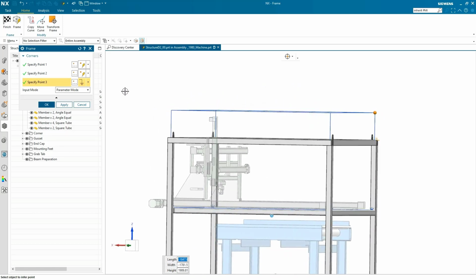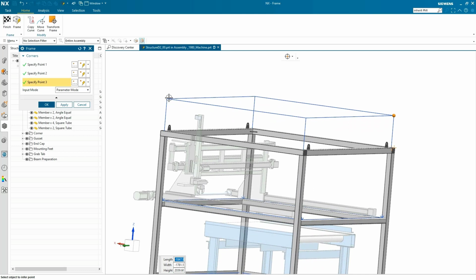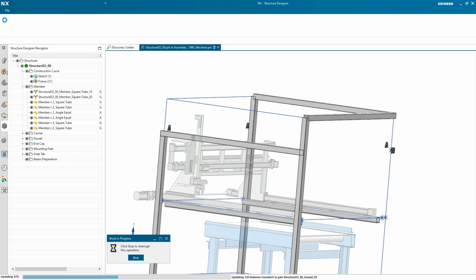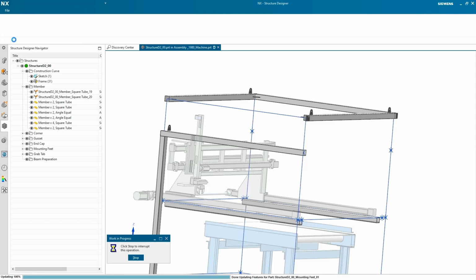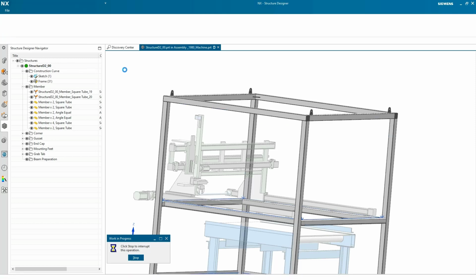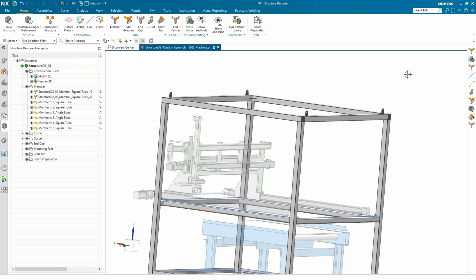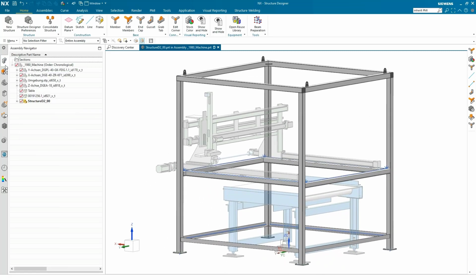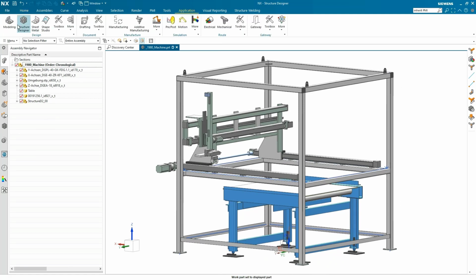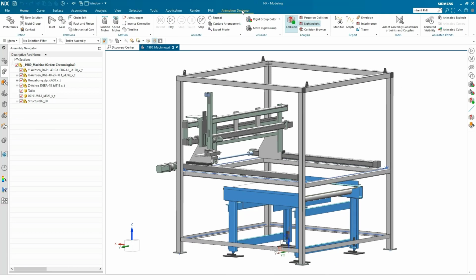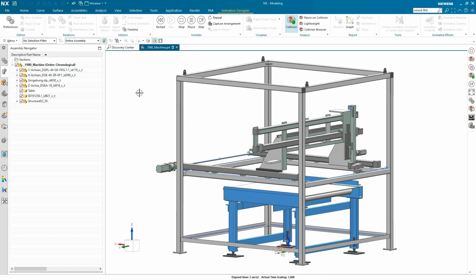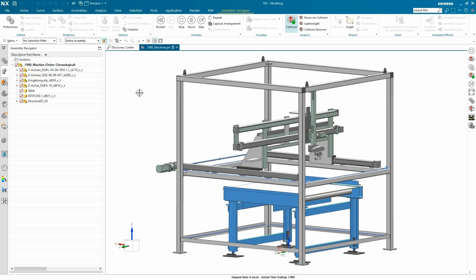Members are changed while retaining specific corner, gussets, caps, and hoist points all update to their required location. This update process also checks members' geometric uniqueness. Should any of the identical grouped members become unique, they will be given their own group. Other types of edits can affect all members. A special command lets you select multiple members, even if based on a different stock, and change them to become the same. A quick replay of the animation shows the interference violation has been addressed. While this interference was obvious, imagine trying to find a more obscure interference deep inside of your model.